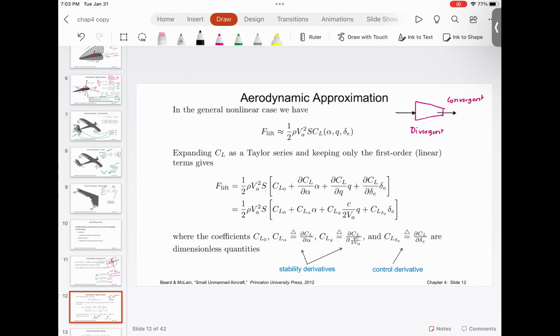Even though air is compressible, for the sake of discussion, let's imagine air is something like a liquid, which means the density or the mass is constant. So since the area here is more, area here is less, we are pushing the same amount of mass. You agree with me? Velocity at exit will be greater than velocity at entry.